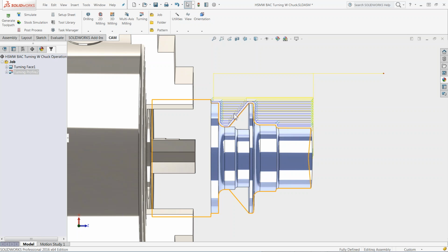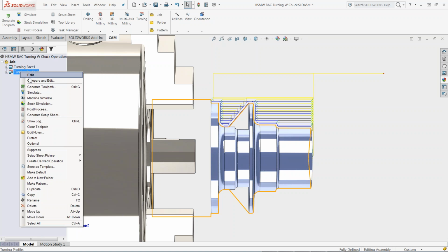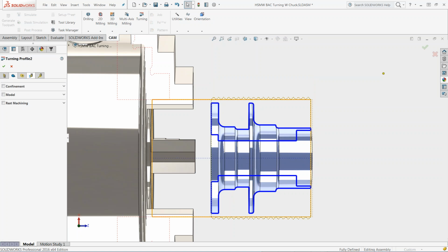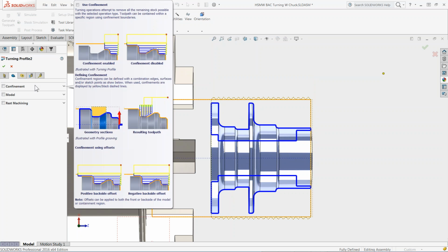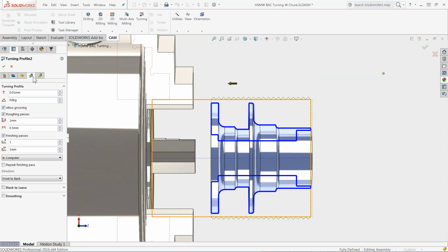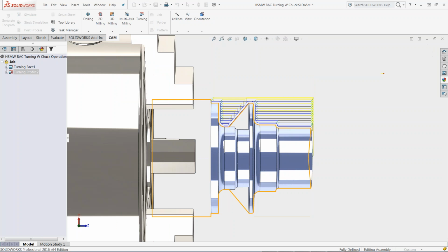So right now, I actually let the tool groove in the back. That is, again, all the options you would expect inside of a full-blown CAM system we have in here. If I go to the Passive tab, I can turn off Allow Grooving, and now you will see that that area has now gone straight over here for when we're doing that portion of it.